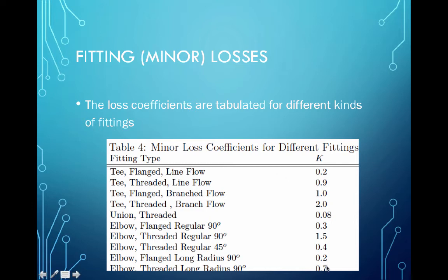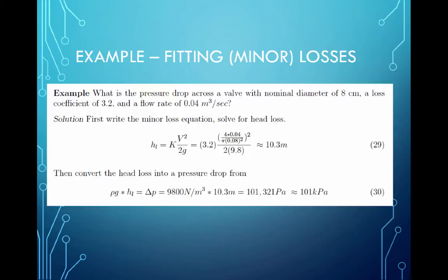Here's a long radius, get the right one. Here's a flange long radius 90 degree, versus a flange regular 90 degree. And so these long sweep elbows that you find at Lowe's for doing plumbing, they're to help herd the waste along down to the sewer system. There is a measurable reduction in frictional loss coefficient. It's not big, but you start adding that up over enough pieces and it makes a big difference.